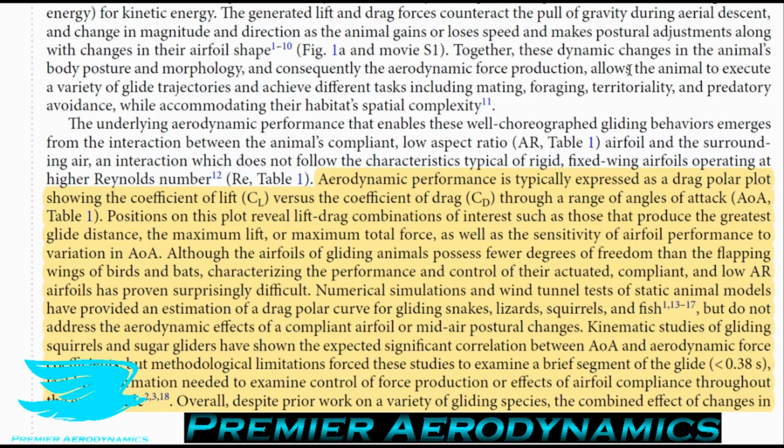Positions on this plot reveal lift to drag combinations of interest, such as those that produce the greatest glide distance, the maximum lift, or maximum total force, as well as the sensitivity of the airfoil performance to the variation in angles of attack. And so drag polars, they're not that common in research, at least. In the aeronautical industry, it's very common, but not so much in general research, even though they are very powerful in terms of what you can glean out of them.